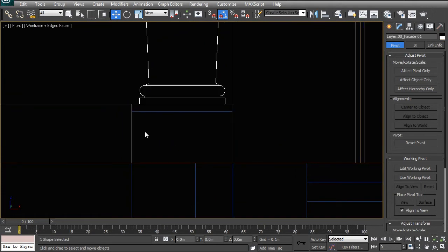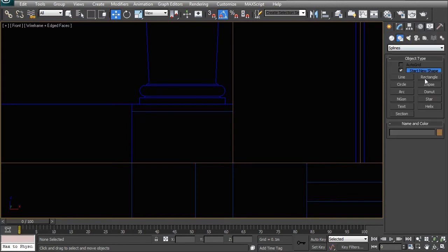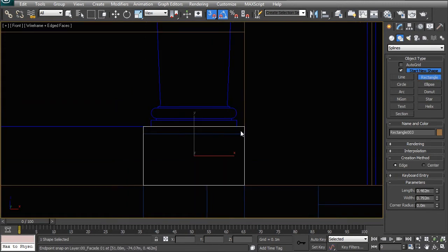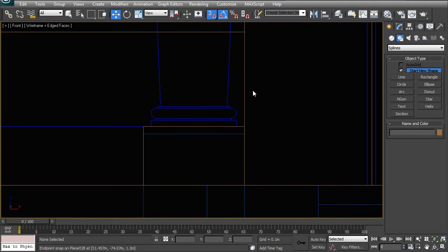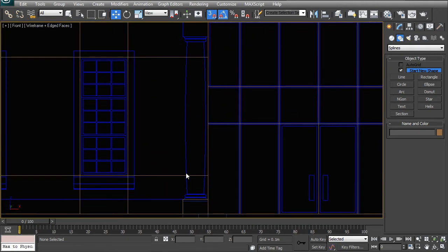And we can do that by, first of all, starting with the square form that you see on the CAD plan. So using the snap command, we're going to take that and then just draw an ordinary rectangle. So nothing too difficult there. Now the next thing to do is to draw the outline of the entire column.